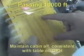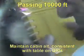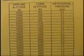Above 10,000 feet, you also have to check a table contained in the Quick Reference Handbook. Search for the Loss of Pressurization Indication procedure in the Quick Reference Handbook, and you will find a table there. The job now is to maintain the cabin altitude consistent with the airplane altitude read on the table.